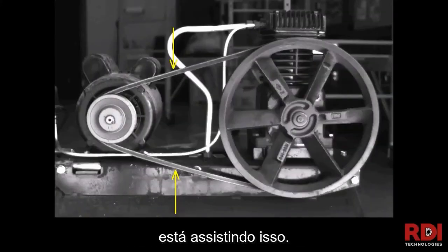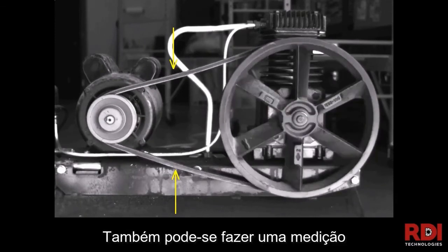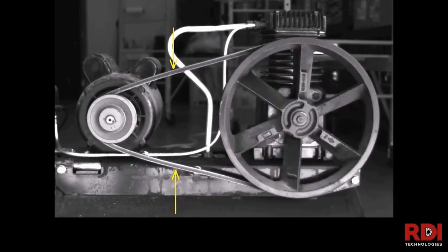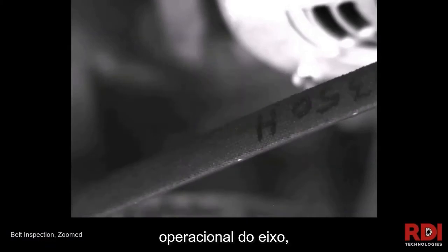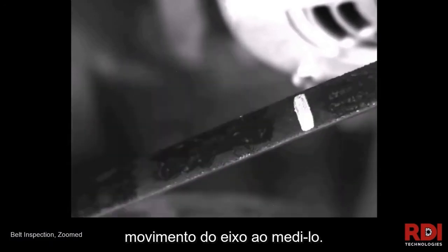And then the other thing, while you're watching this, I'll just speak to this. We're getting the belt here. You can also do a displacement measurement on the shaft as well. So you can actually measure the operational run out of the shaft in addition to just this inspection. So you can quantify the motion of a shaft when you're measuring it, right?